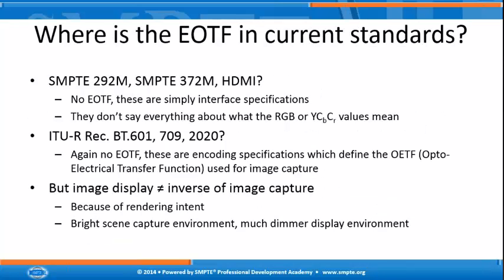So the first question is, where is the EOTF in current standards? If we look at things like typical SMPTE 292, SDI standards, 372, or even HDMI, there's no EOTF in these. They're basically interface specifications.